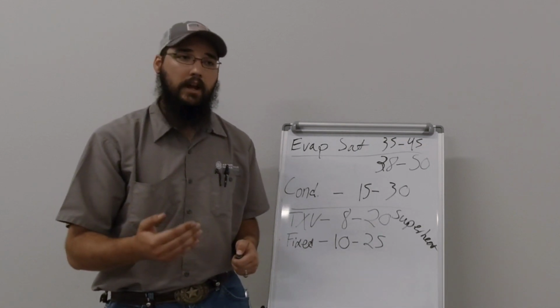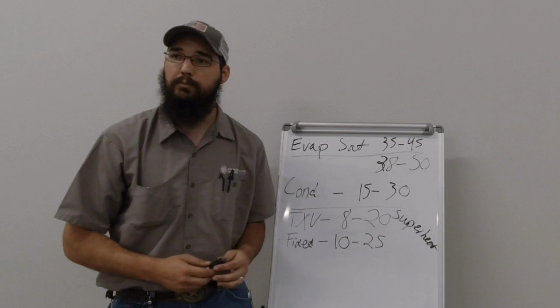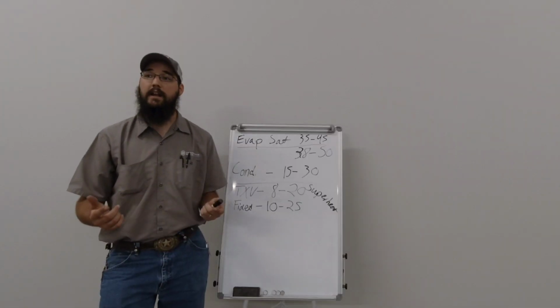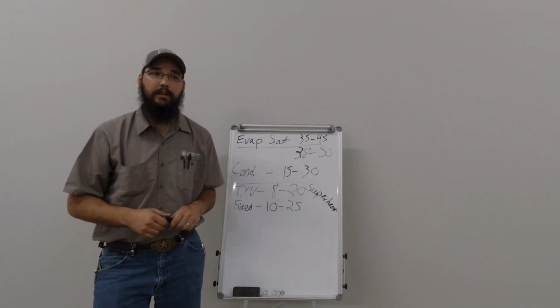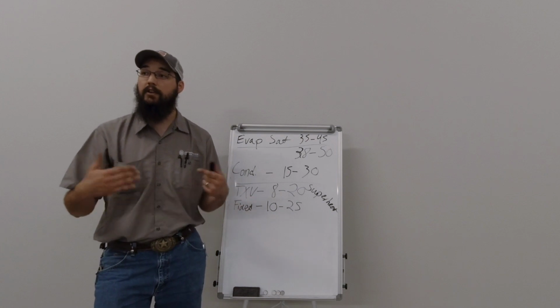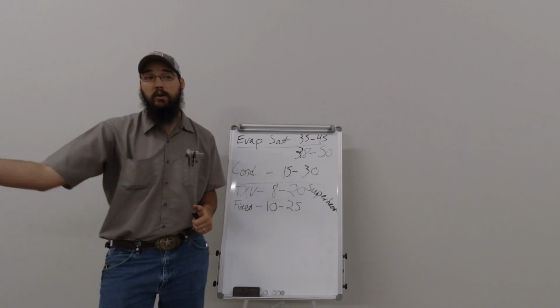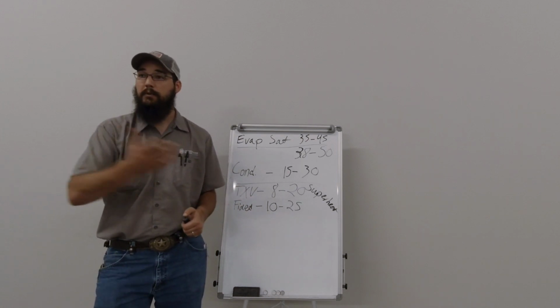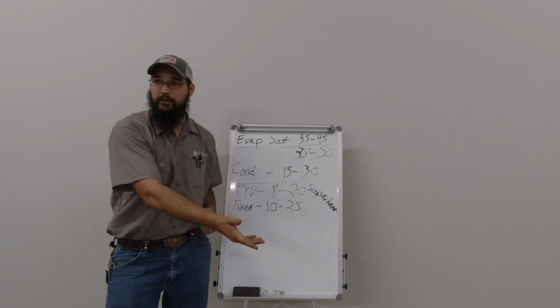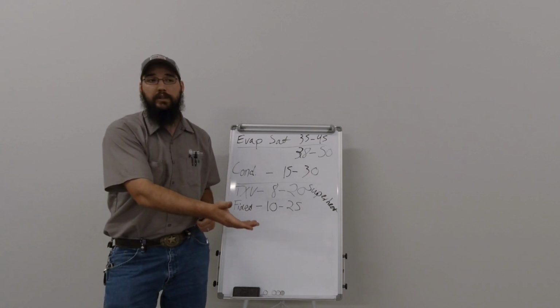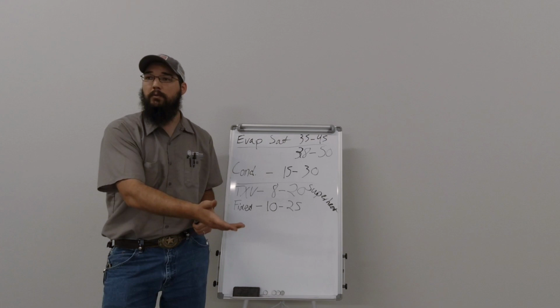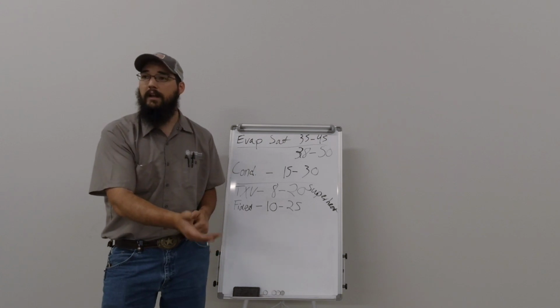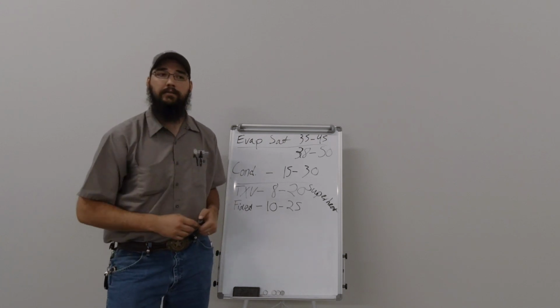of circuit 1, and now all of a sudden I've got a 5-degree superheat. Well, my next step is I need to increase that superheat, because it worked fine with the one compressor, but when it came on with its own compressor, the 2 compressors together working the same circuit were overpowering the valve. And I need to help that valve out by pinching it off some.